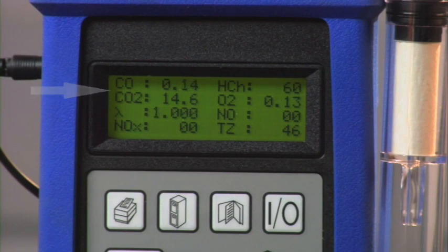One thing to keep in mind, a lot of these vehicles today are so complex with VVT, tumble valves, and electronic throttles. It's very hard to do some of these tests, like wide open throttle conditions or holding the idle at 2,000 RPM. Do the best you can. Sometimes you may have to push the gas on and off during some of these tests to load the converter up, because you want to feed it as much fuel as you can in order to get the accurate test results you need out of these catalytic converters.